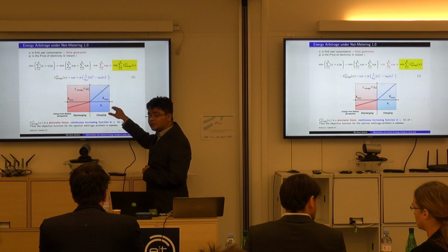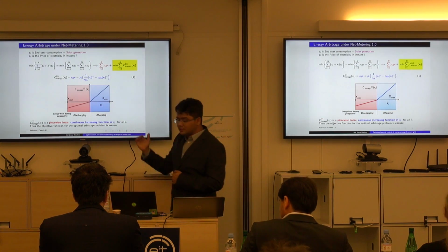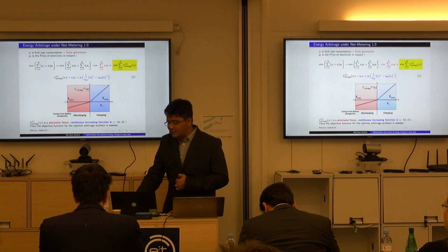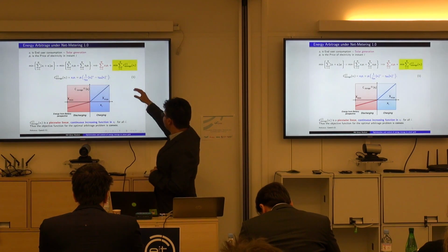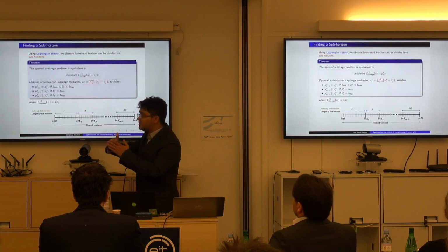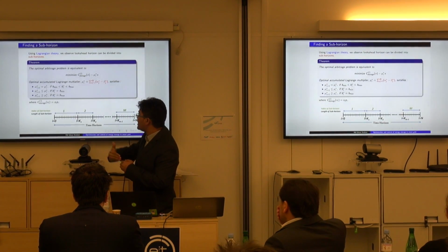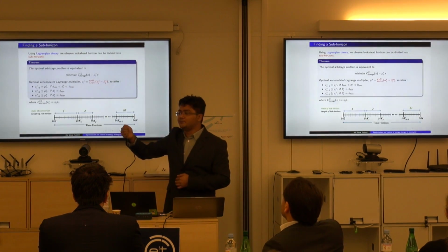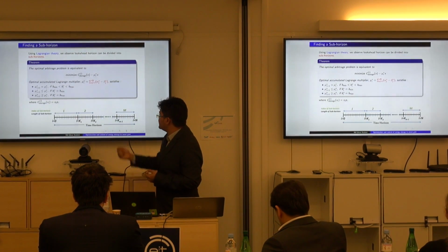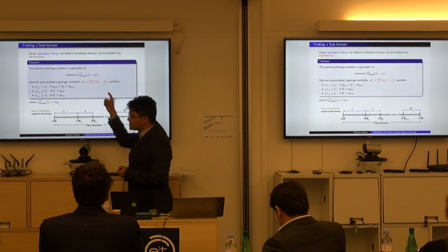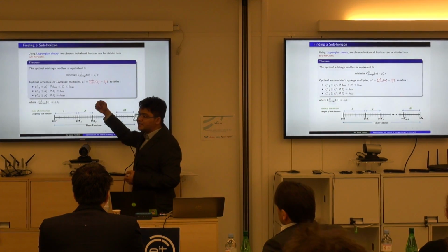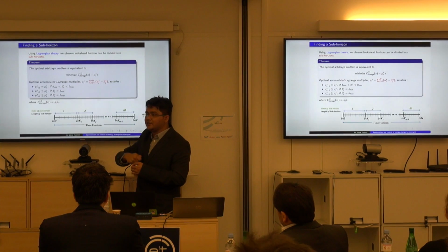Whether the cost function is convex or not depends on what decision variable we select. In this case, we select xi, which is the change in the charge level at time instant i. If we use strong Lagrangian theory and simplify this, we observe that the optimization function, which ranged from time instant i to n, can be reduced to a point-by-point minimization, in which mu i captures the future variations of prices. Mu i is the accumulated Lagrange multiplier, which is the summation of all my Lagrange multipliers, and these alphas and betas are associated with the battery capacity violating an upper or lower boundary.